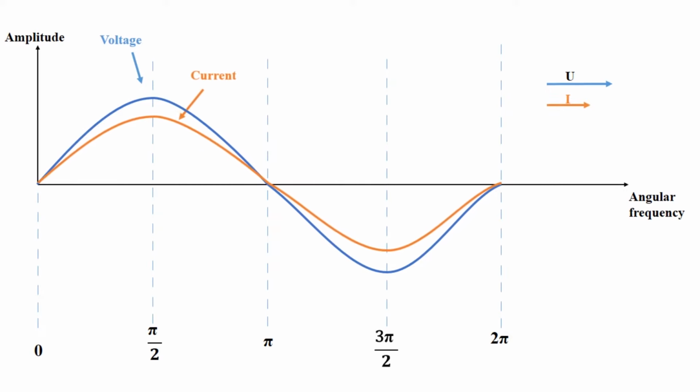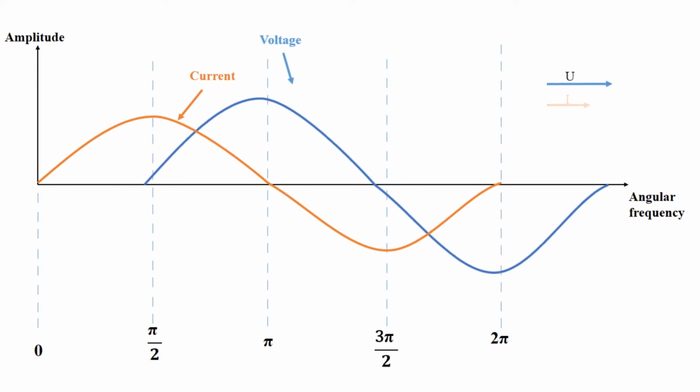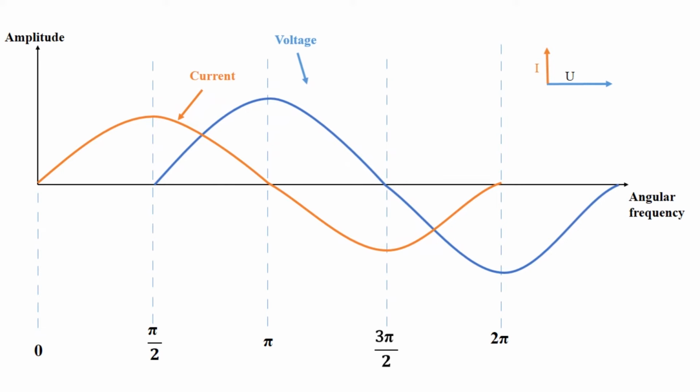In a capacitive circuit, the situation is reversed. Voltage is lagging behind current by half of pi. The phase angle is still 90 degrees, so only reactive power is flowing in this example as well.